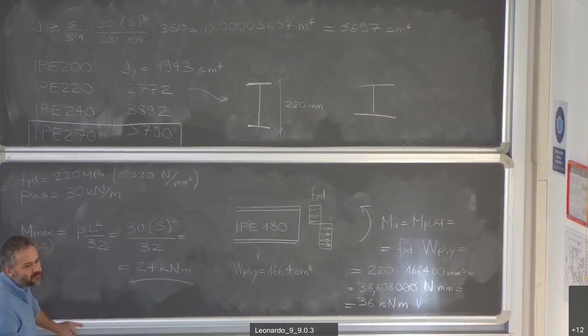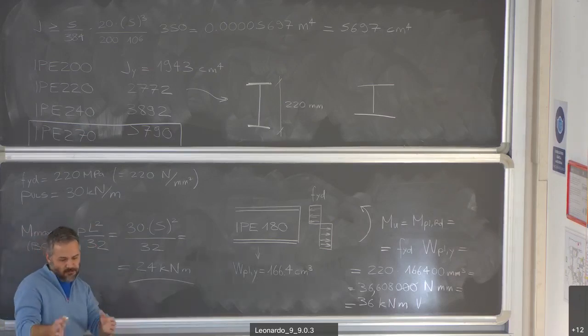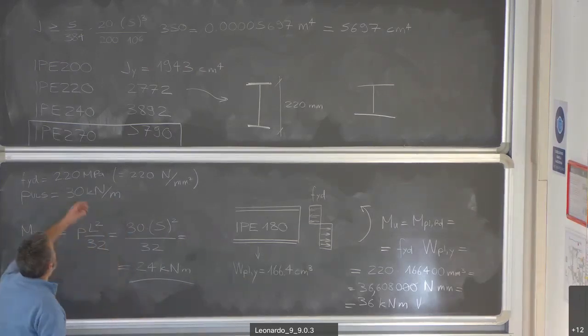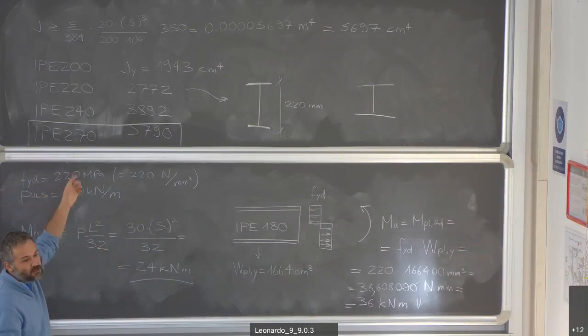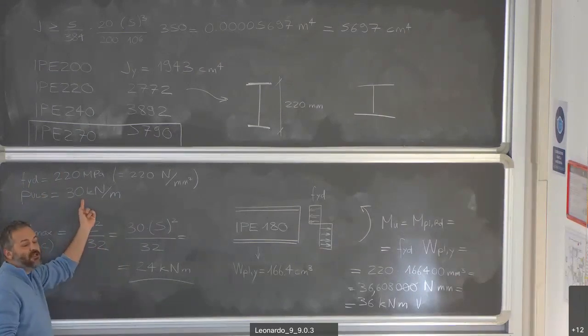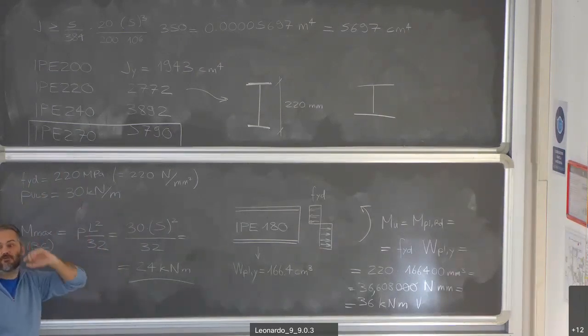Do these include safety factors or no? When I give it to you during the written exam, not in real life, regardless of the exam. In real life, you have to work out from the basic loads the ultimate limit state load. Just to give you an idea, previously we had 20 kilonewton meters. It's a serviceability load. If you go into ultimate limit state load, it means it's a load which is much higher, 50% higher.